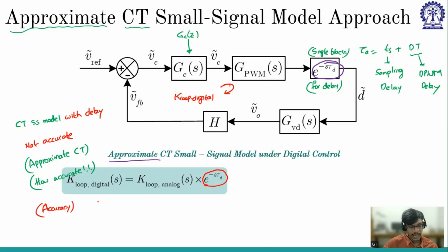So when we are saying small signal model, we are approximating what? Ripple. We are neglecting ripple. Ripple information is missing, right? So it is not the actual signal. Ripple information is missing. So that's why in the previous course, Sir was matching the small signal model versus actual switch simulation.